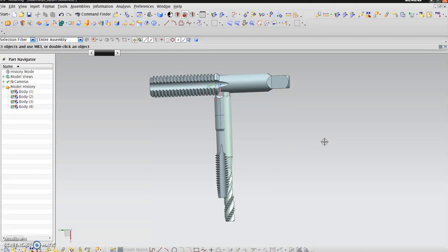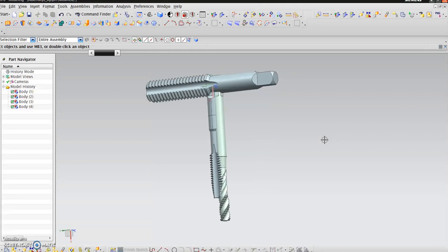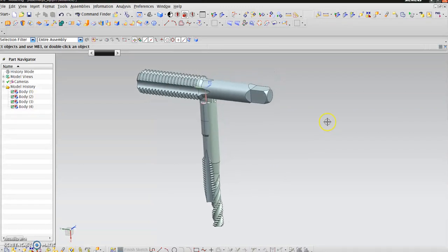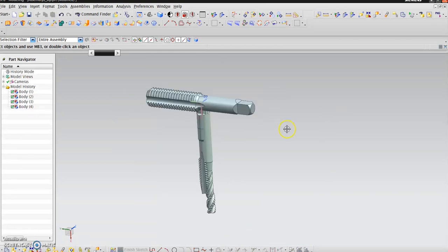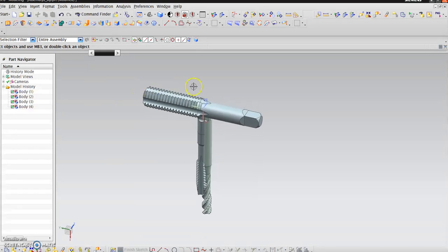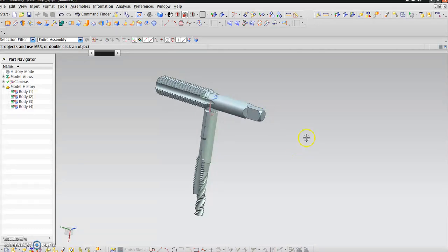The most commonly used materials are high-speed steel, cobalt, and carbide. High-speed steel is the most commonly used for drill bits in simple applications such as carpentry and a lot of simple day-to-day use. Most of the carbide tools are used on expensive high-speed CNC machines. Depending on the application, cutting tool manufacturers will opt for high-end coatings. Basic coatings such as bright finish, black oxide, and TiN will be used for not very demanding applications.